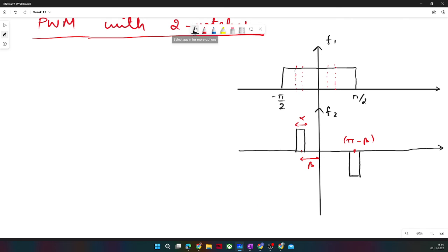Again, I will give one more pulse so that I make it more distributed, as you might have seen in machines also. Earlier, it was concentrated at one place, so it was producing maximum magnitude of back EMF or induced EMF. If you recall from machine concepts the winding factor concept, when it was concentrated winding, it was producing maximum winding factor of 1. If you remember, Kw1 used to be 1 for concentrated winding.